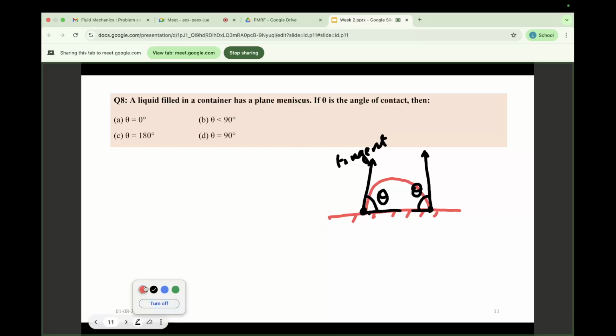Sometimes the surface is not flat. It may happen that the surface is uneven. In that case, you have to take several readings, like 10, 20, or 50 readings, according to the surface roughness. After that, you have to average out these values and report a fixed value. For a flat surface, one angle is sometimes sufficient, but it is advised to take at least 10 readings.